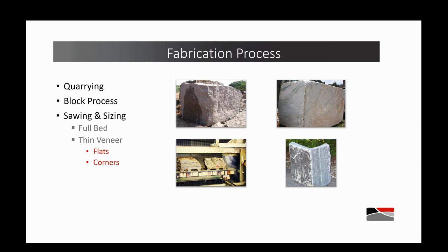They do that more recently with a chemical compound, which is, the stone is drilled, the compound is poured into the drill hole. The drills are at various centers along the stone, and then as that material dries, it expands and causes a uniform crack along the quarry, and then those pieces are taken out from there.